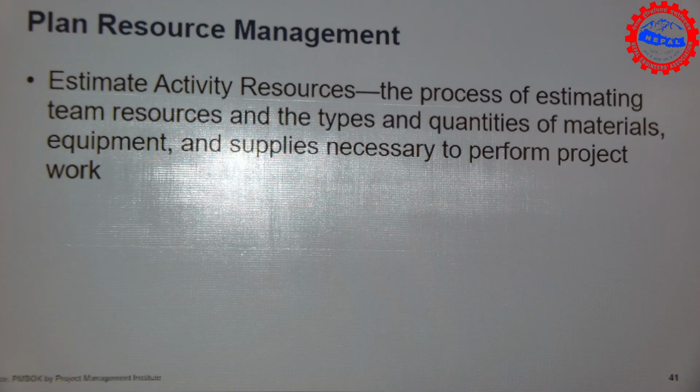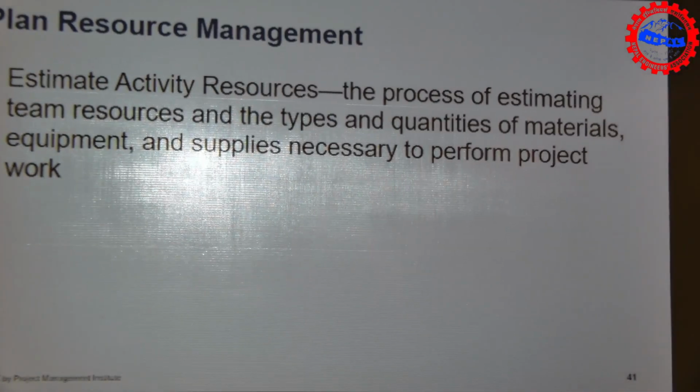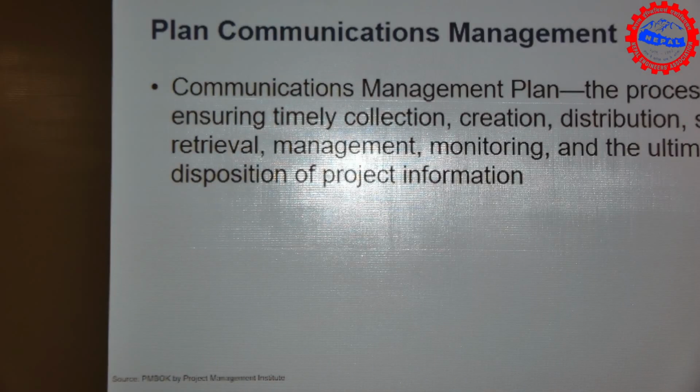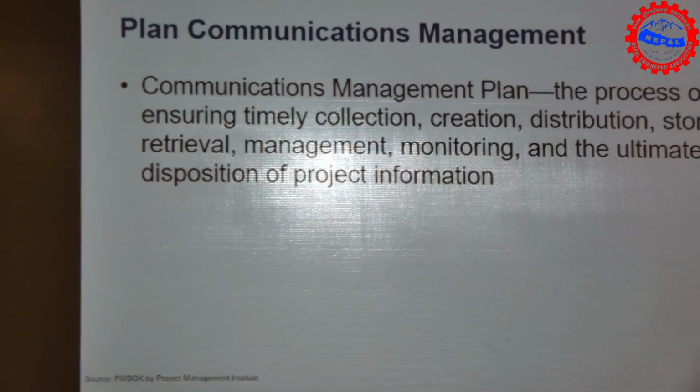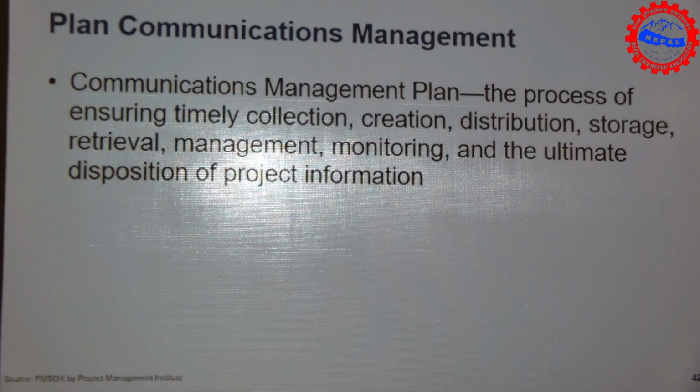If you're talking about productivity, do you estimate that the same person does, for example, 5 square meters per hour? The productivity will be different on Monday and different on Friday. Morning 8 to 12 will be different, afternoon will be different. There is a big fluctuation. But when you're making the estimate, the assumption is that you are just dividing equally. When you say you have 5 square meters per person and 5,000 square meters of painting, you simply divide, right? So when you're dividing by the productivity norms, you need to consider average productivity, not maximum, not minimum, to consider all those potentials. I hope some of you, if you are involved in project planning, have considered that. At the same time, all the communication management is about collecting the information, how to store the information, how to manage and monitor it, and ultimately.